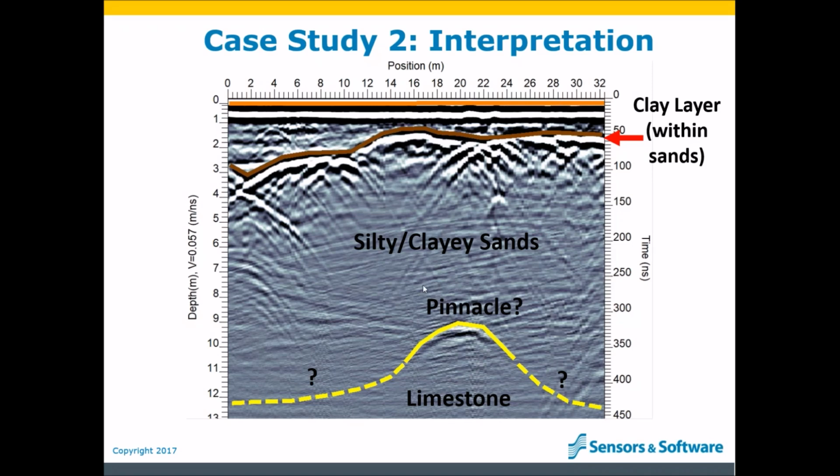A simple definition of coherent is that we see a pattern for the signal from GPR trace to GPR trace laterally. This airwave is visible on multiple traces, so it's a coherent signal. Again, stacking improves coherent signal. It does not reduce it. Let's look at another example of coherent signals that we don't want in our GPR data.